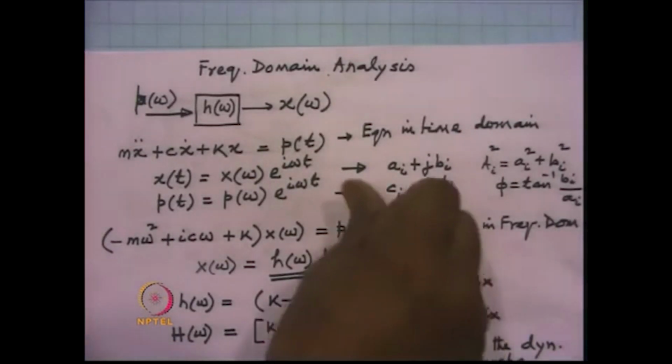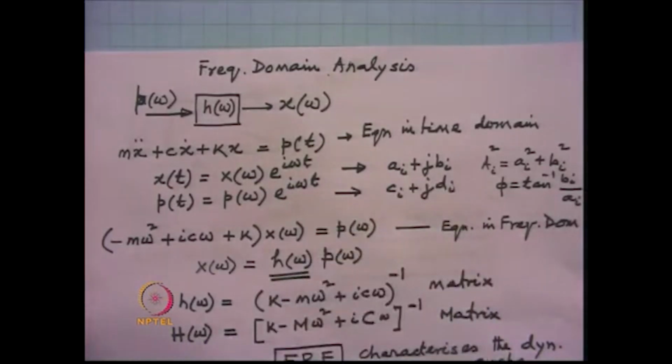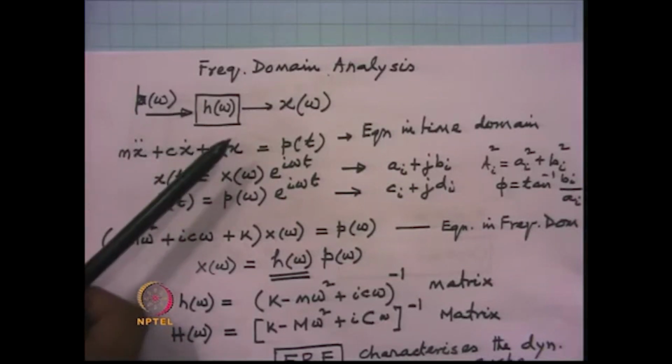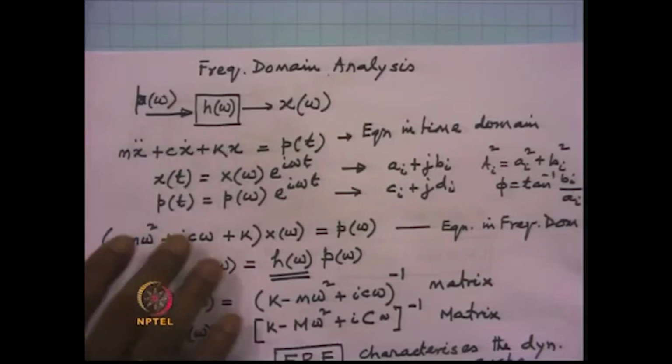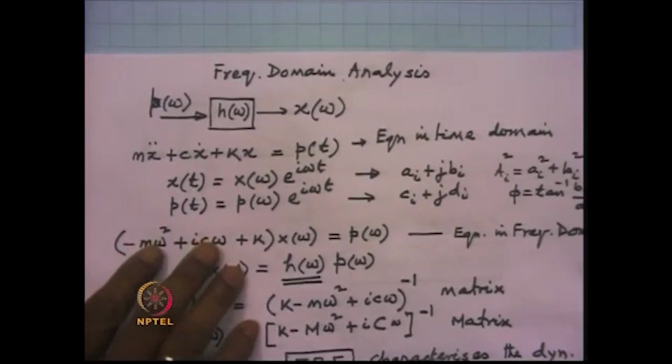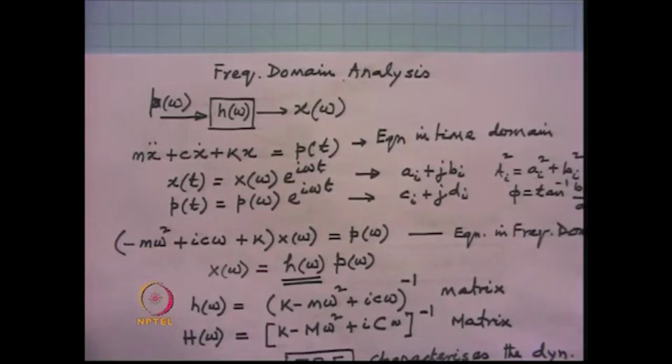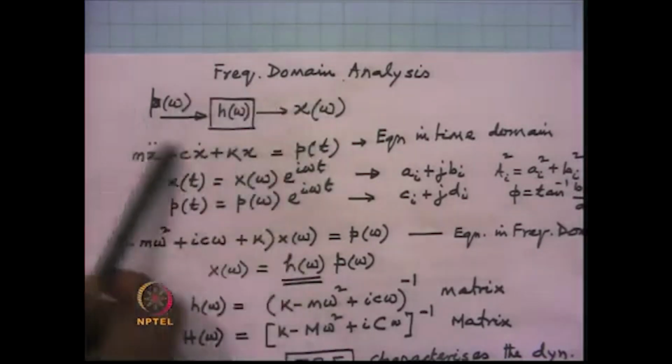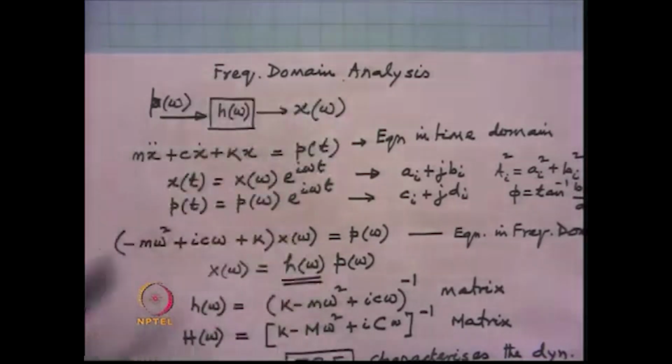Using that concept, one can find the frequency response function of a single degree of freedom system, or of a multi-degree of freedom system by a frequency response function matrix. This is highlighted over here with the help of this diagram.